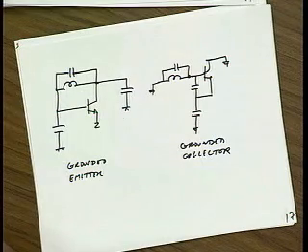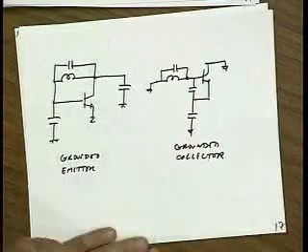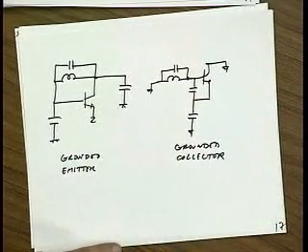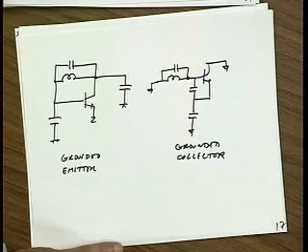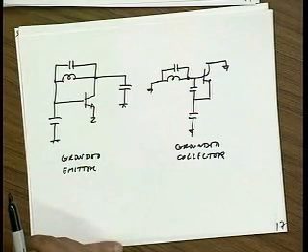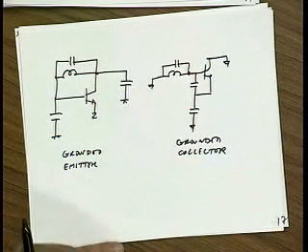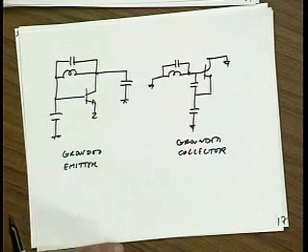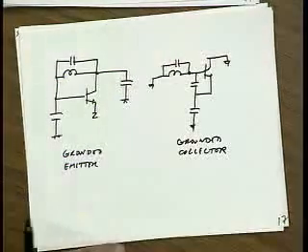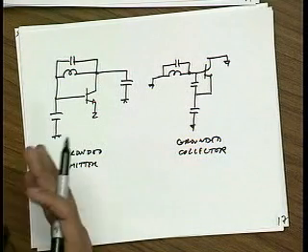LO leakage. So by definition, this is an oscillator, so LO is everywhere, right? There is no leakage. I mean, you have sharing the same ground with other. Oh, I see what you mean. That's actually a very good point. So let's defer discussion, because right now we're just talking about oscillators in general. Later on, we'll see, to build a robust oscillator, first of all, you'll probably go differential. So we could take all these circuits and turn them into differential equivalents to try to minimize basically supply noise